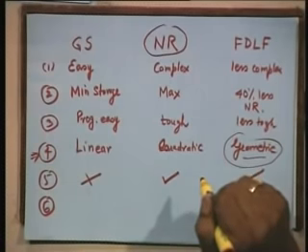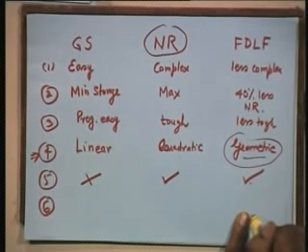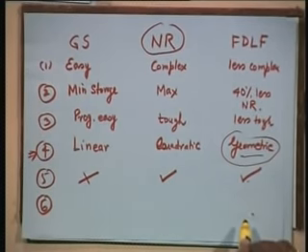The time increases linearly with system size in Gauss-Seidel, whereas in NR it hardly matters whether it is a 3 bus, 30 bus, 300 bus or 1000 bus, more or less it converges in 3 to 4 iterations. Here it takes 5 to 6 iterations, because convergence is not quadratic but geometric. That is, geometric is in between linear and quadratic. So, this is about system size.